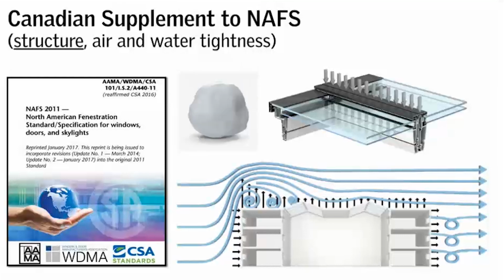So your snow loads are going to be that downward force. It's a bit counterintuitive, but the downward force is positive in this application. And then you have your upward force, which is your wind. And we have to design for anticipated local conditions.